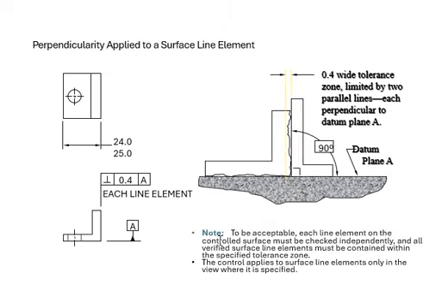Of course, to be acceptable, each line element, meaning like just a control, is always connected. Here, in this case, you have 2 parallel lines. We always refer to your tolerance zone, which is this one. That's all we're talking about, even if you're studying the same thing with different terms. Just make sure that whatever you're measuring is within that tolerance frame, because this one completely controls it, and that's why the name is a feature control frame. This frame controls that feature.